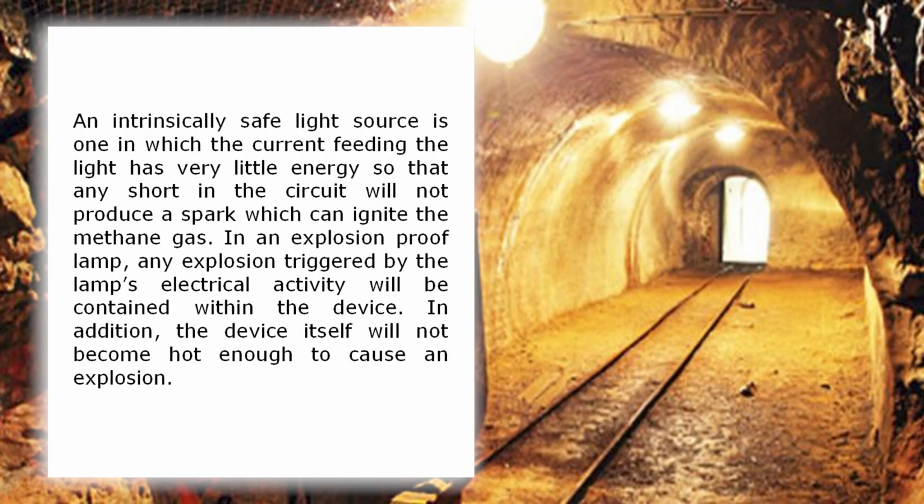An intrinsically safe light source is one in which the current feeding the light has very little energy, so any short in the circuit will not produce a spark which can ignite the methane gas. In an explosion proof lamp, any explosion triggered by the lamp's electrical activity will be contained within the device. In addition, the device itself will not become hot enough to cause an explosion.